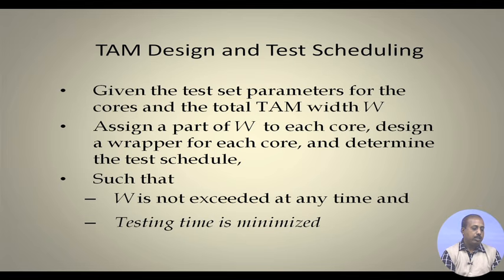Anyway, the test time has to be minimized, and this test time minimization is one of the constraints. The other constraint we can have is the power limit: at any point of time the total power consumption of the system should not exceed the power budget for the chip. We can also have a total energy limit, the time multiplied by power, summed up to give the total energy.